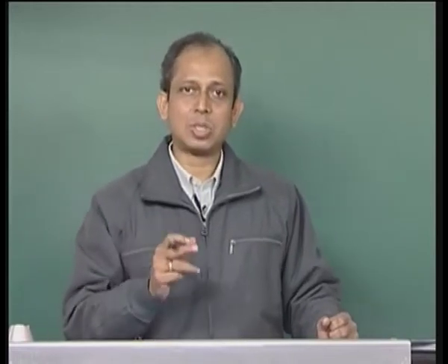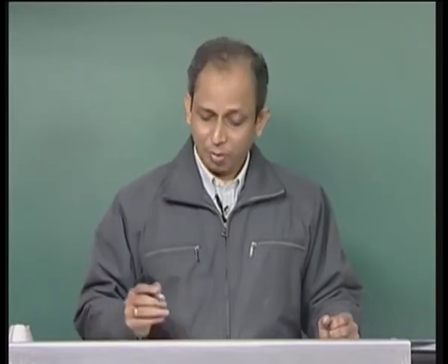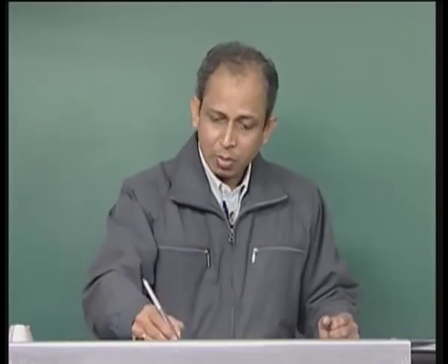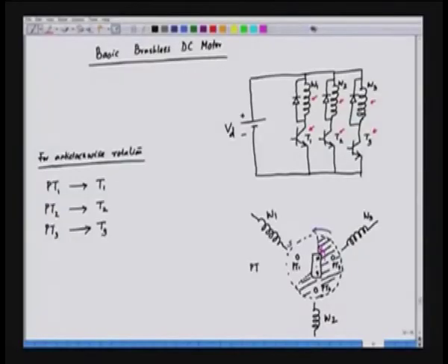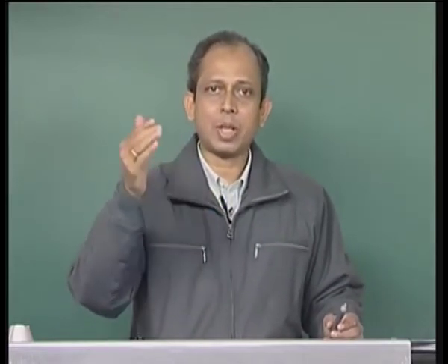We have 3 phototransistors and we have a disc, partly opaque and partly transparent, and in this case we make this 120 degree. This is 120 plus 120, so that makes 240 and this is 120. So, when we make this disc, 240 will be opaque and 120 will be transparent. So, this disc will be pressed onto the rotor. It is glued on the magnet. The rotor is basically a magnet having a south pole and a north pole.